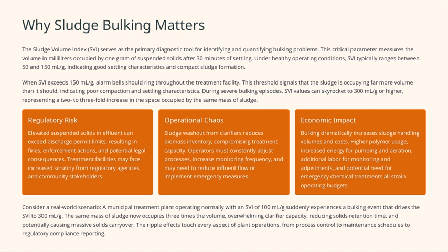Economically, the impact is just as significant. Bulking means handling more sludge, which drives up costs: more chemicals like polymers, more energy for pumping and aeration, and additional labor for monitoring and adjustments. Sometimes, we might need emergency chemical treatments, which only add to the expense.